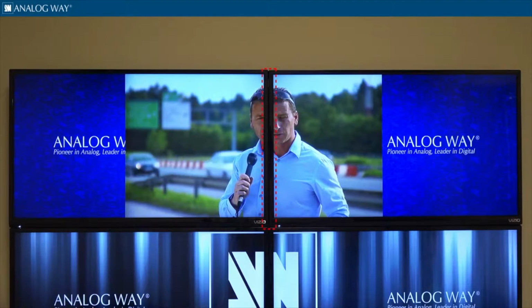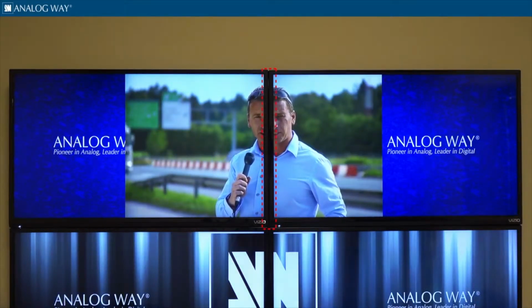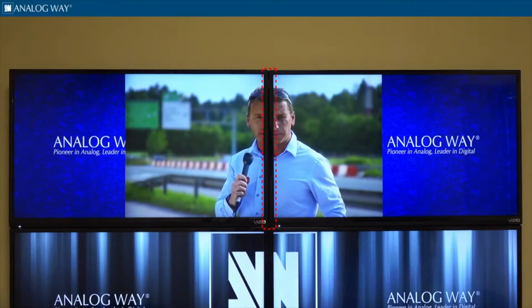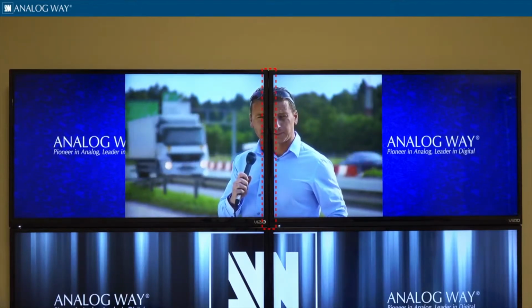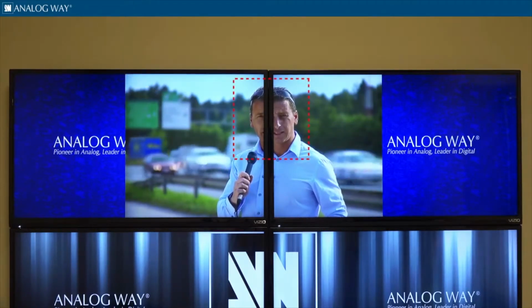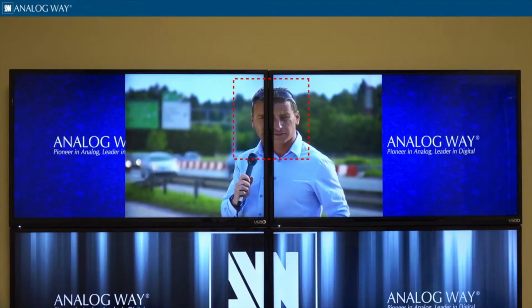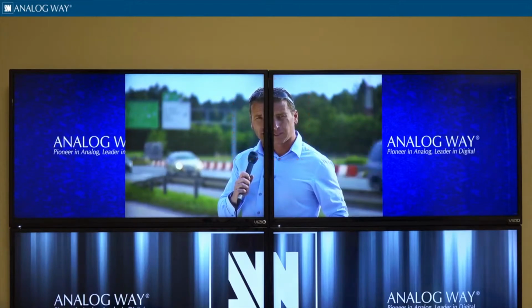A display array with bezels has a unique issue of physical separation between quadrants that does not have any active pixels. If these pixels are not compensated for, video aberrations will be obvious in the form of a gap, or tear, between quadrants. A diagonal line will look unnatural as it passes through a quadrant. A person's face will look noticeably wide and unnatural. Video will also lose cohesion between quadrants even though the signal is perfectly synchronized.